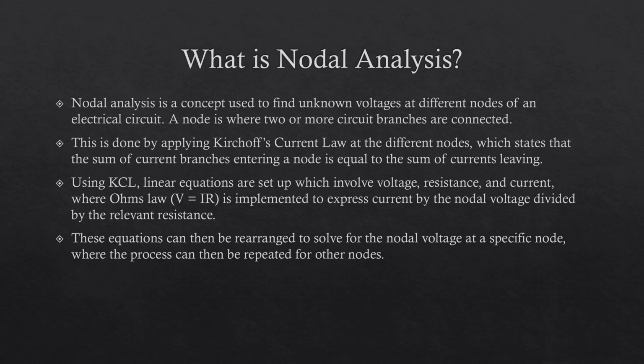Using KCL, linear equations are set up which involve voltage, resistance, and current, where Ohm's law is implemented to express current as the nodal voltage divided by the relevant resistance. These equations can then be rearranged to solve for the nodal voltage at a specific node, where the process can then be repeated for other nodes.